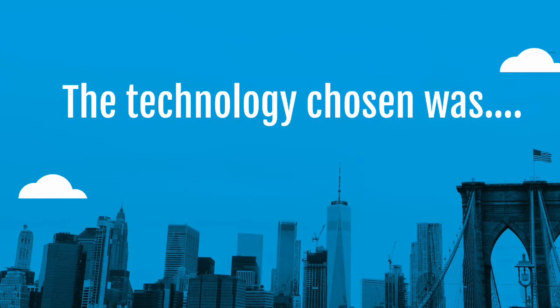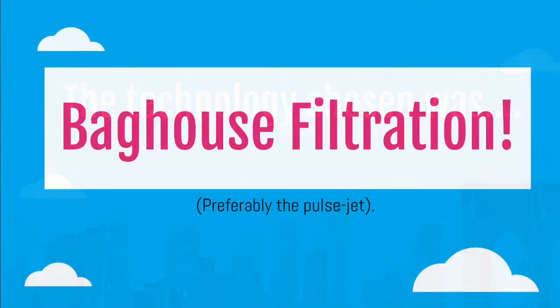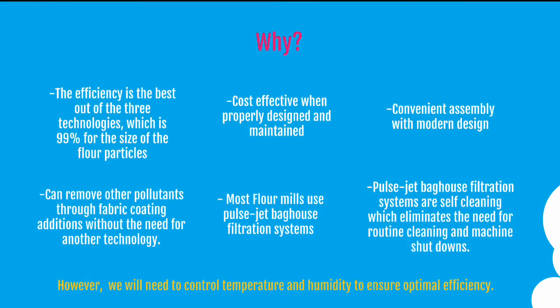The technology chosen was baghouse filtration, with a preference for the pulse jet cleaning system. Baghouse filtration was chosen because its efficiency was the best out of the three technologies, which was 99% for the size of the flour particles. It is the most cost-effective when properly designed and maintained. It also has convenient assembly with a modern design. The system can also remove other pollutants through fabric coating additions without the need for other technologies.